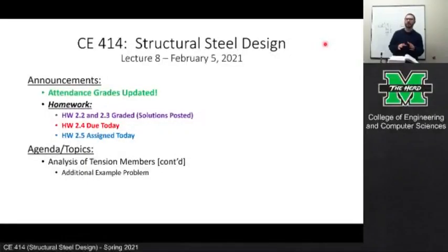Unless... Well, I see what you're saying, and the reason that the manual says that, you can even look in Table 2-5, is that you can get different behaviors of steel based on its thickness. As plates get really, really thick, sometimes the ultimate tensile stress is capped just by the metal structure that you get from a plate that thick, like if you look at the structure of the atoms.